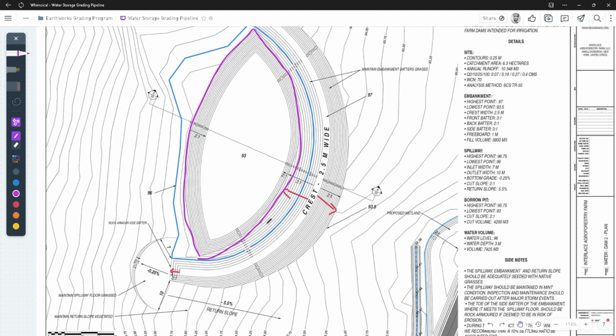That's okay. Your job isn't to make things work. In reality, it's just to analyze a concept and see if that could potentially work. But in any case, this is something that we have to do at this stage. We need to balance out these two as much as possible, because that will dictate if this dam is even going to work. If the volumetric analysis reveals that there's just not enough material to build a dam, then you have to go and talk to the client, and you need to inform them about this so that they can make an informed decision of whether they want to continue the project, and if they do, what compromises they are willing to make.